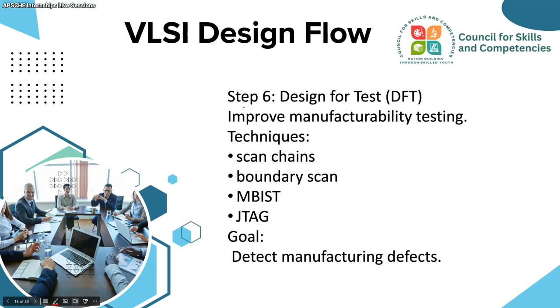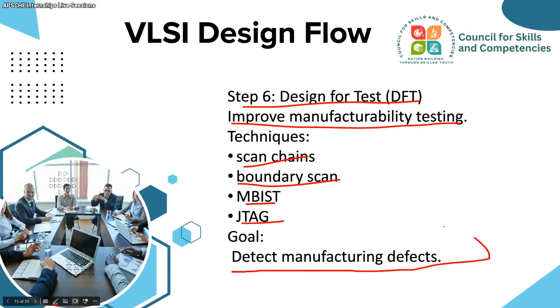So next comes the design for test. It will improve manufacturing testability by scan chains, boundary scans, MBIST, and JTAG. So it will detect the manufacturing defects. That is the design for test.